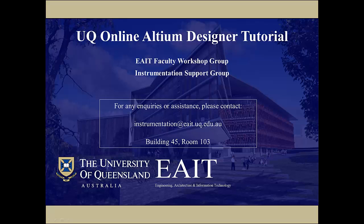The PCB document is where the physical PCB is designed. Altium uses the schematic document to work out which component bodies are required and which pins are connected together. However, it is up to the user to physically lay the components out in a usable manner and lay the tracks out appropriately, in a way which avoids electromagnetic noise and inefficiencies.